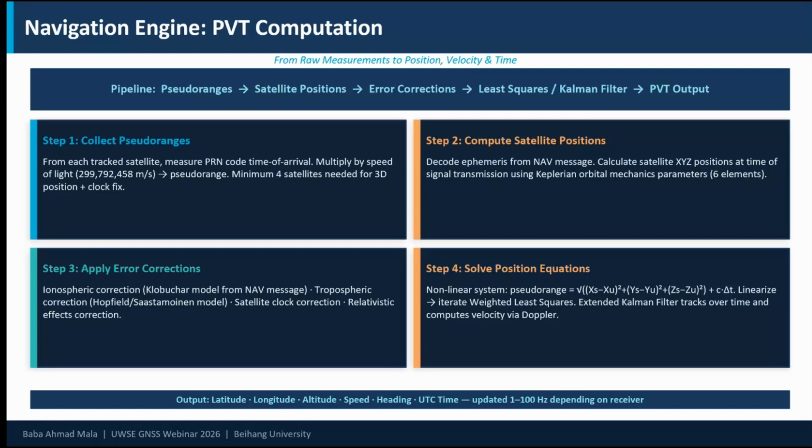And then next you move to solve the position equation, which is a nonlinear system equal to pseudo range, linearized into an iterated weighted least squares, plus an extended Kalman filter that tracks over time and computes velocity via the Doppler.